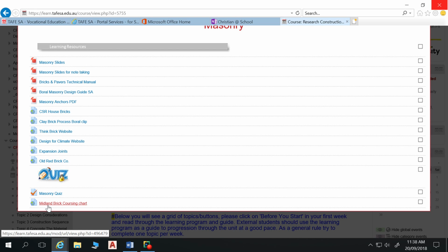This one is a standard brick. Wow, surprising. So your standard brick is 230 long, 76 millimeters high, 110 millimeters wide. That 230, 76, 110 is a very important number to remember, because that dimension ends up carrying through your building so much.